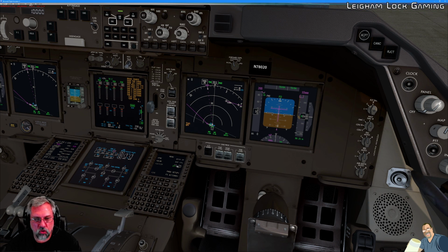I'm going to go ahead and turn the control panel back on just so I don't forget about it. We have programmed the flight management computer, so we do have V-speed indications already on the speed tape. You can see V1 135 is already listed here.